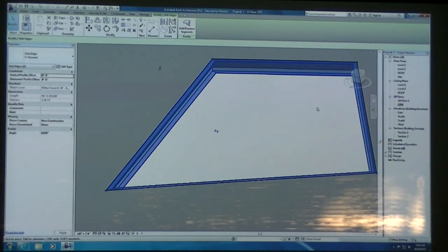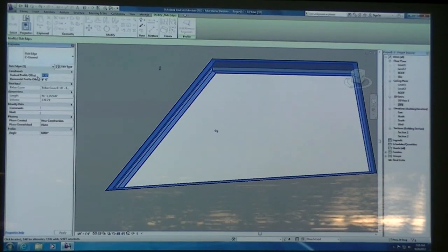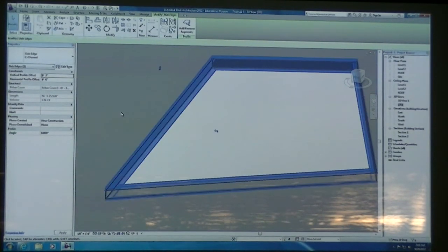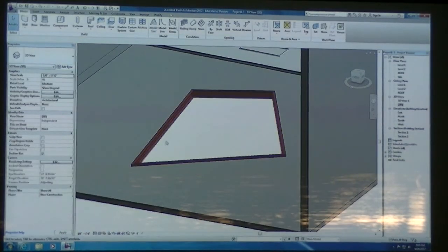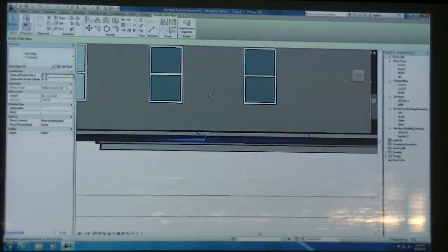If you select that 3D element, when you actually apply that, you get these flip handles, so you can flip your shape just in case your profile happened to be backwards. And then over to the left, you also have vertical profile offset and horizontal offset. So if I typed in 2 inches under vertical profile offset, it basically moves this whole profile up 2 inches. And so you can apply and set this to whatever kind of edge or condition that you'd like to see.